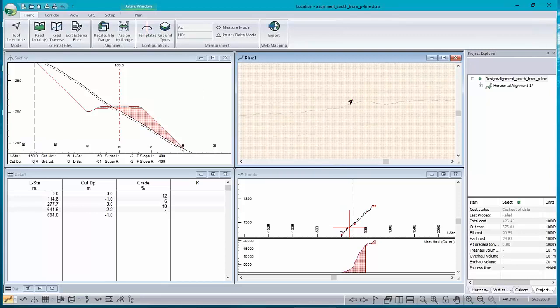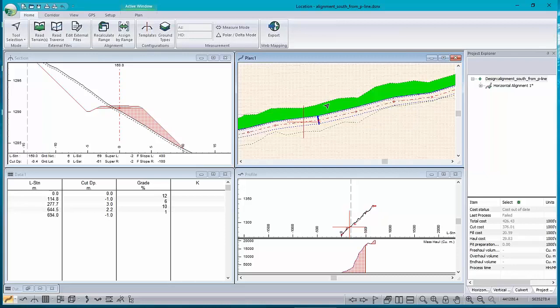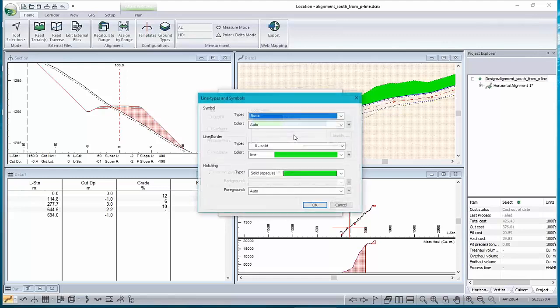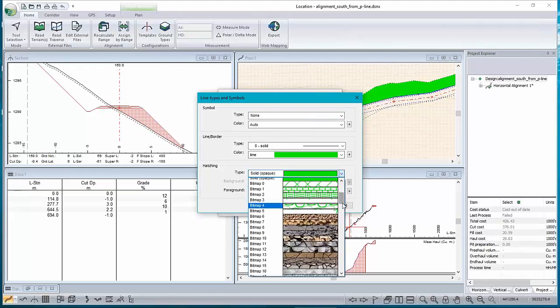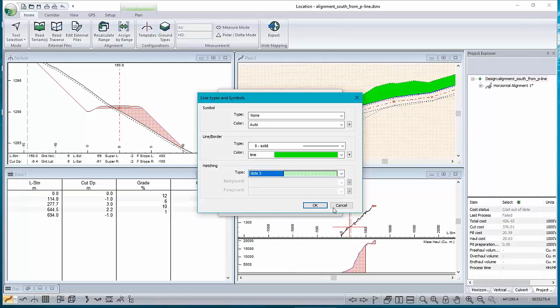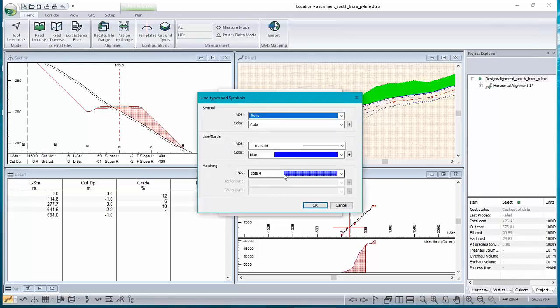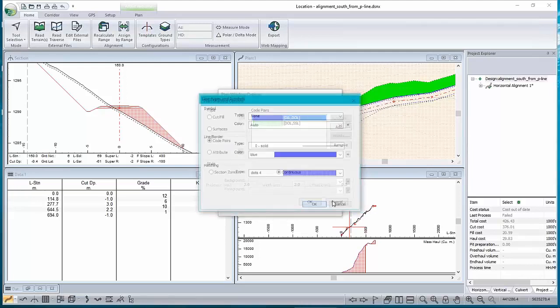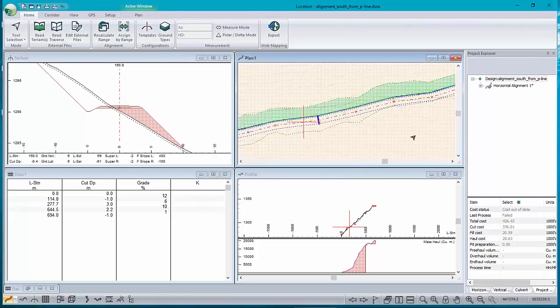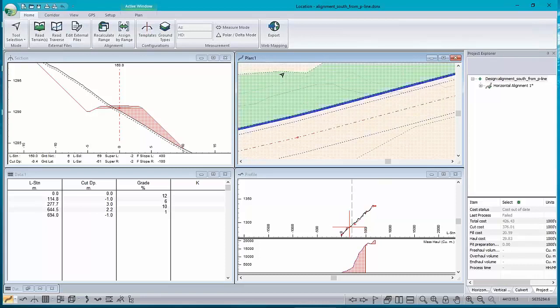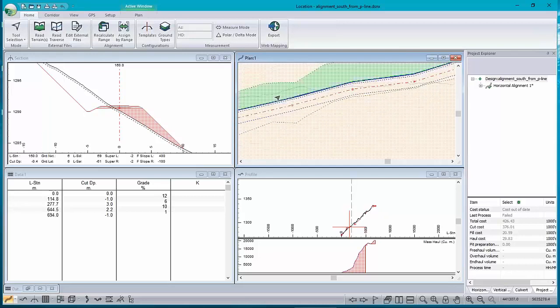Okay, I don't know if I've chosen the best hatching parameter. You can change those here as well. So that one's currently set to solid opaque. Let's change it to something transparent. That'll look a little better. Same here. No, dots 4, that's a good one. Okay. Yeah, now I can see through it. That's better. There's my ditch bottom. There's essentially the exposed cut bank. Maybe you want to seed that. That's an area that you might want to seed so you can see it.